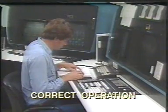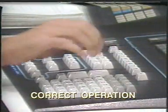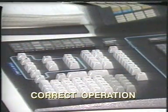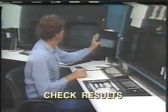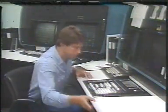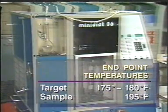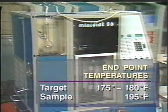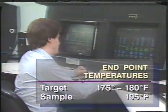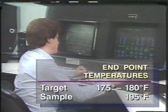If so, he considers all the different ways it can be corrected, chooses the best solution, and makes the necessary adjustment. Finally, he checks the results of his action to make sure the problem has been resolved. Suppose lab tests show an overhead product has an end point 15 degrees higher than called for by specifications. An operator quickly increases the reflux rate to remove heavy material from the overhead product.